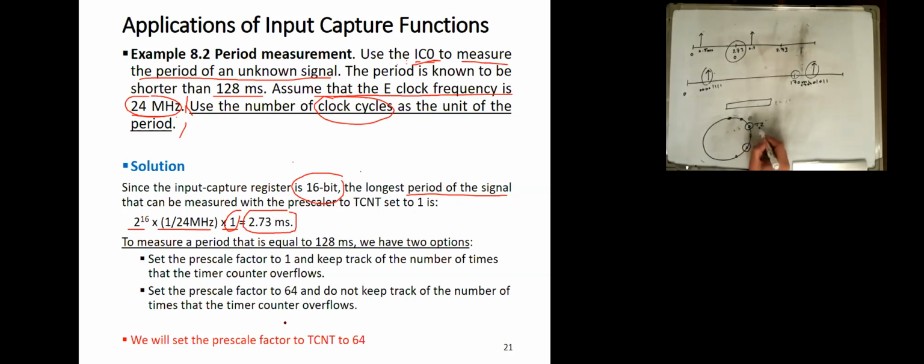Basically, you will count how many increments you needed to reach here. So this is what is meant by modulo subtraction. So T2 is less than T1, so the time will be negative, but this is true for the usual subtraction. For modulo subtraction, no, you are taking this.